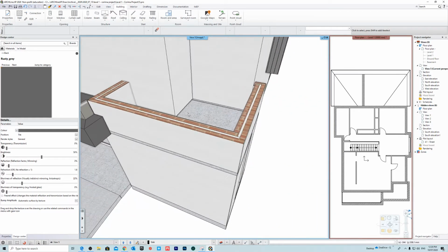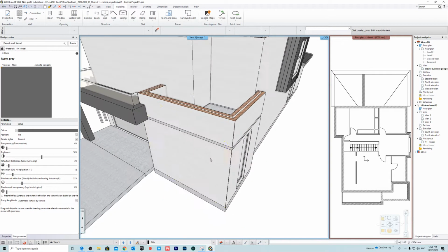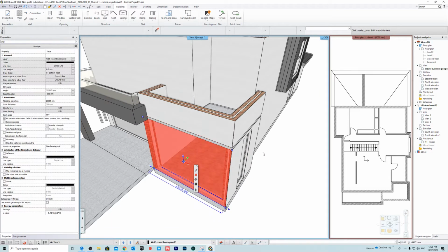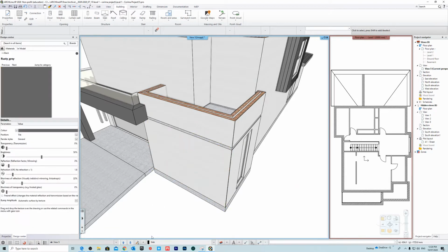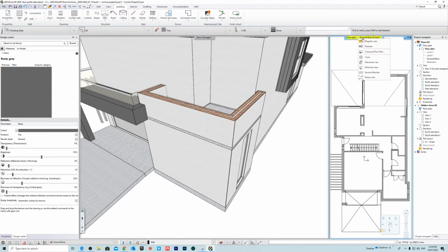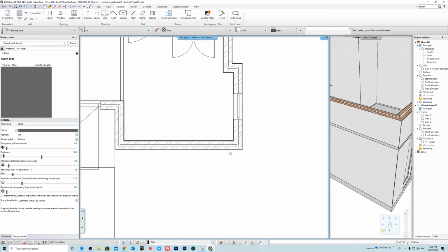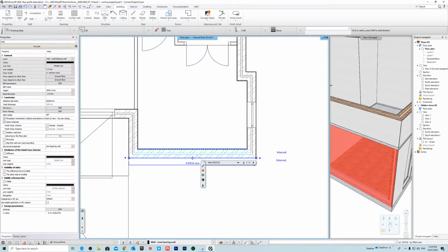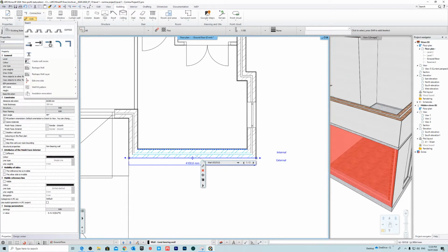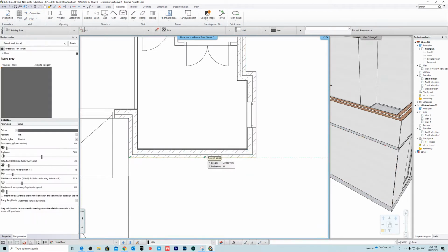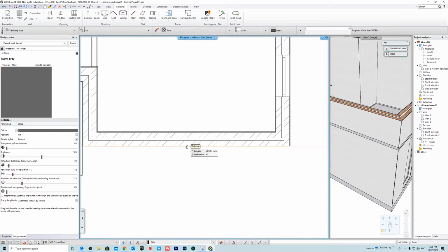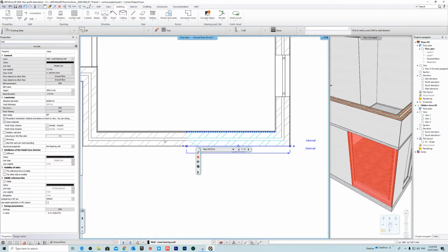render layer. Okay, and we need to create a small layer that's going to go right to the bottom. So we've got to split these walls into two. Okay, so that's what we'll do. We'll go to level 1, ground floor I mean, and we're going to split these in two because there's a special little feature wall coming right across there. Okay, so to do that, we're just going to click on this. We'll go edit, and we're going to go insert endpoint, click the outside edge, and we'll make it around about there. Okay, so we have 2 walls now.